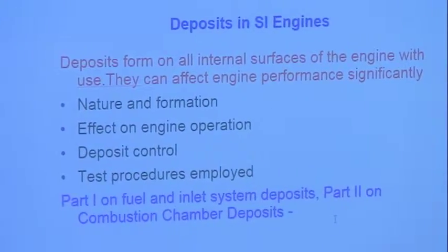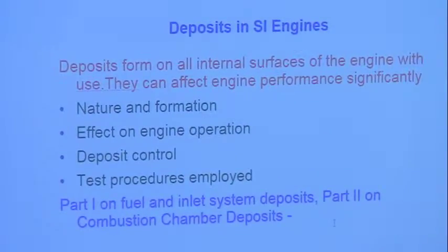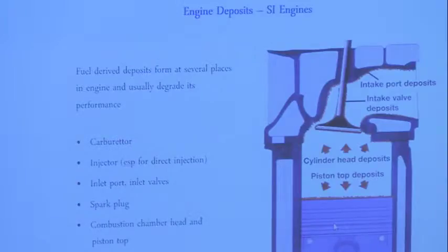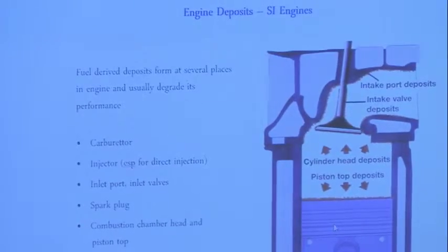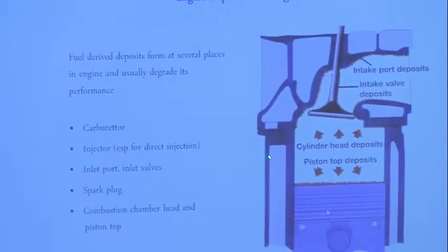not an exact science. I'll first look at fuel and inlet system deposits, and then at combustion chamber deposits, which are really relevant to spark ignition engines. I will come to why it is so. In spark ignition engines, deposits can form on the valves, on the fuel system, and in combustion chambers.